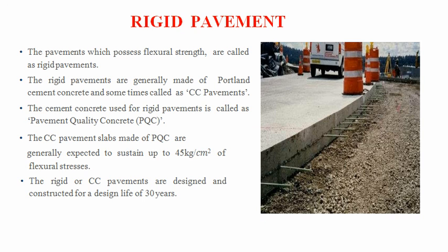Rigid pavements are pavements that possess noteworthy flexural strength or flexural rigidity, that is, the resistance offered by the material against deformation. The pressures transmitted from the surface layers are not transferred by grain to grain action, as was the case with flexible pavements.